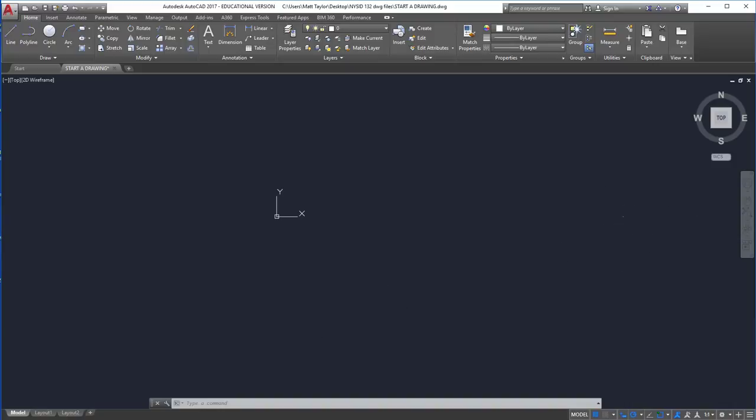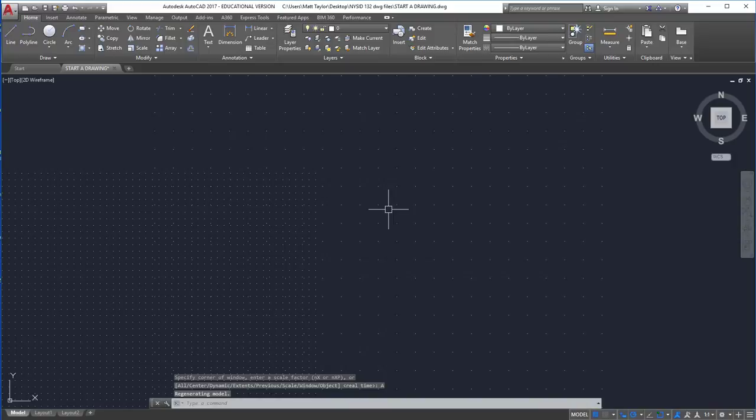Well, if you look on our handout, all the way at number 5, it says zoom all. This will help you get the whole grid on the screen. Just type in Z, enter. That's a zoom command. And then A, enter is the all option. So it's zoom all.